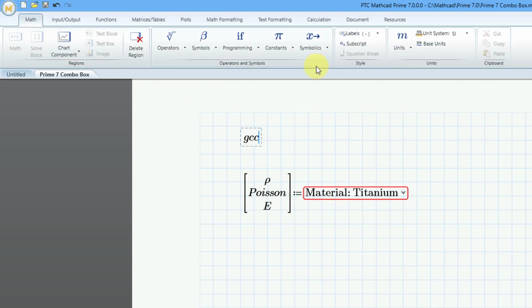Now I'll go back to the Math tab, and I've got to change the label. I'll change the label from automatic, because if I leave it automatic, it's going to think this is a variable. I'm going to change this to unit. You'll notice, if you have good eyes, the color changed to the standard blue color for units. Then let's use the definition operator, and this is going to be equal to grams divided by centimeters. Then I'll use Shift 6 to get the superscript, and let's put in a 3 over there.